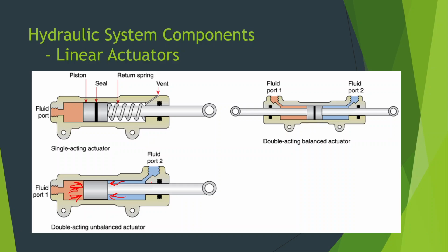Landing gear, right? You need probably more force to put it up, and then gravity's helping you when you bring it down. Most of the time, again, landing gear, that little bit of force, all it's doing is pushing it into the lock position once gravity's gotten it most of the way down. And even that often is taken care of because you have slipstream you can use to lock the gear down. Or the cargo door was the other example.